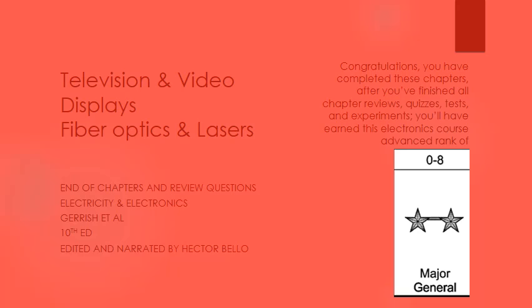Third generation devices use sensitive materials such as gallium arsenide, or GaAs, as the photocathode. This allows more efficient conversion of light to electrons at lower light levels. Also, the MCP in these devices is coated with an ion barrier film to increase tube life. Third generation devices are more sensitive, smaller, and provide better resolution than their predecessors.